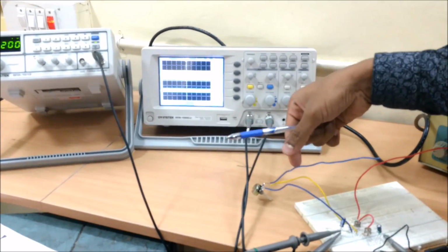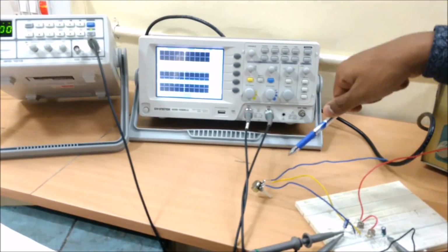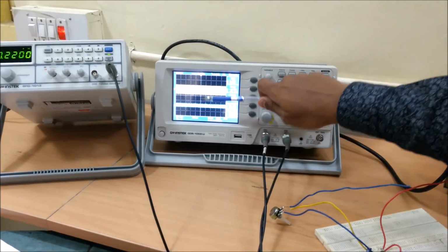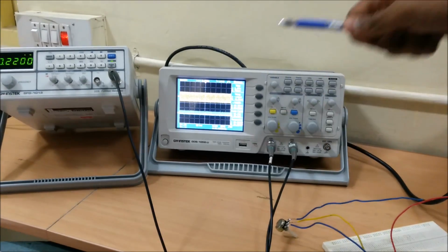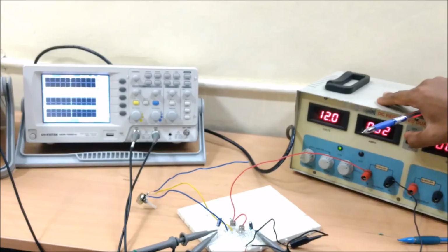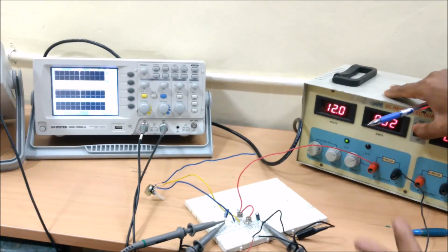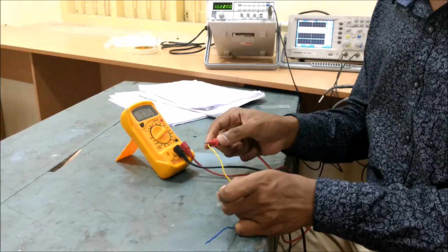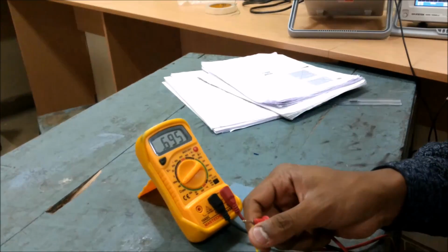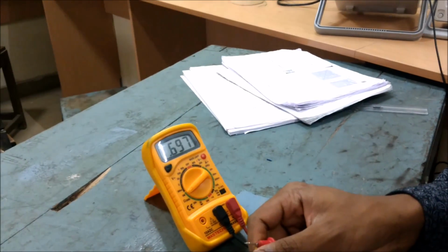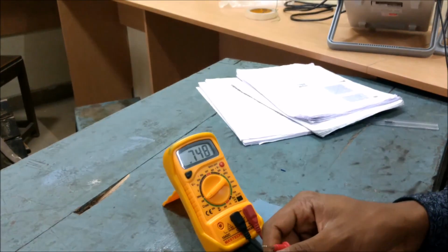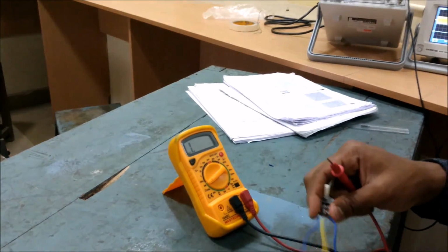Guys, now I connected the pot and we can see that at a certain level, the output exactly reduces to half of the input. Now we can measure the resistance by using a multimeter, and conclude what the input resistance is. We can see that we are getting almost 700, that's in the 2 meg range. That means it's almost 700 kilo ohms. That's in kilo ohms.